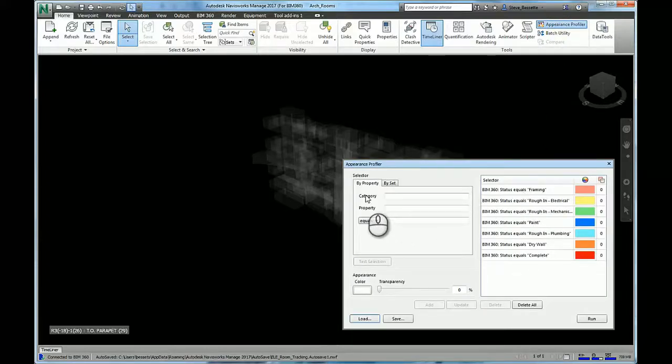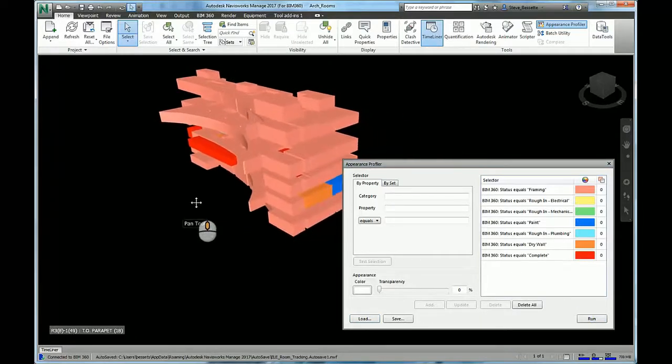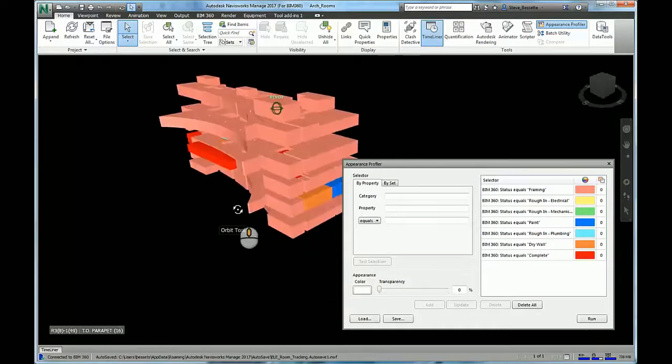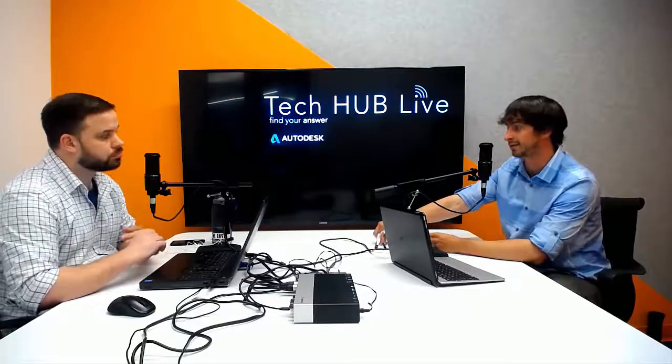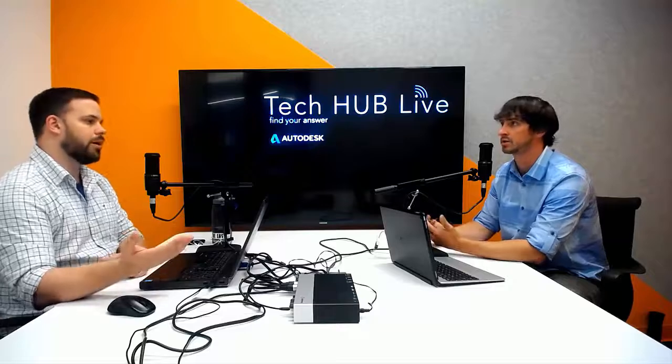And what does this do? Again, it's giving you that 3D visualization, right? I think Revit does a great job of the preset floor plan views that you can kind of, again, get that overlay on a plan, but doesn't have that 3D component because the rooms just don't carry through in a 3D component in Revit. So I think that's a good application of Navisworks, and I really like the idea you said earlier, right? I can do this to room status. I can do this to number of issues, number of checklists that are open, really a whole number of different things I may or may not be concerned about. So it really lends that flexibility to get that insight on my project just through the color variations. There's the flexibility. It allows you not to have to boil the ocean to be able to utilize this kind of workflow. Right.